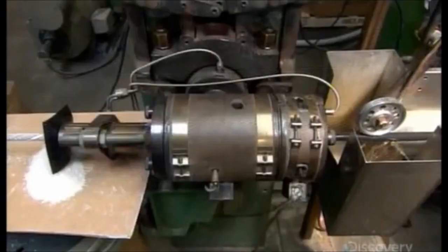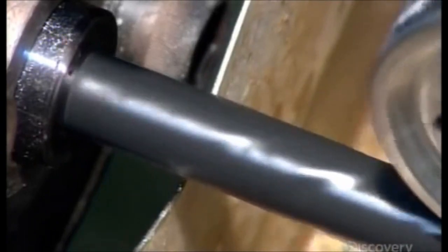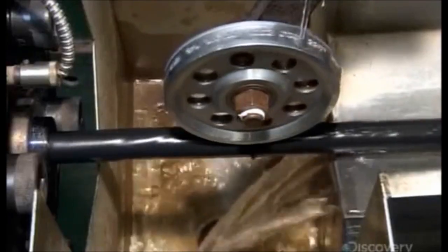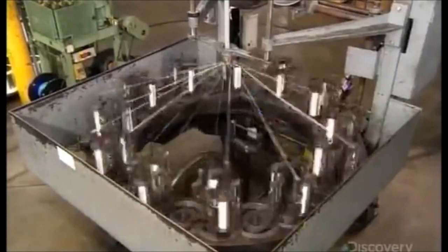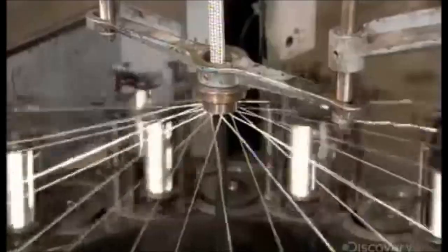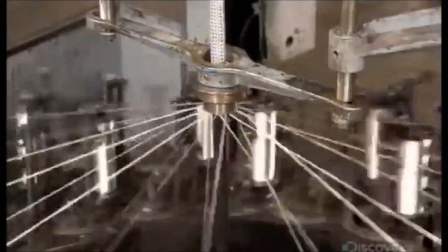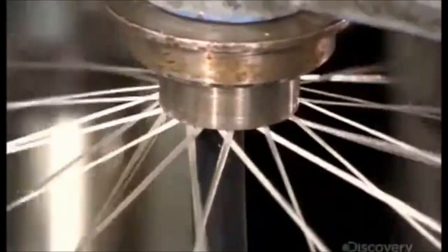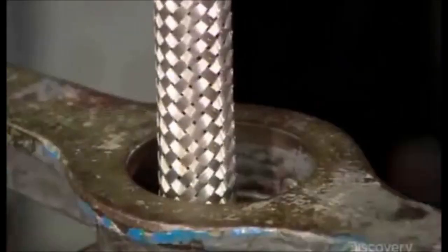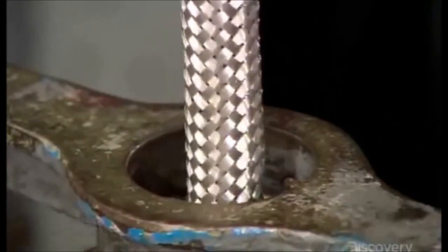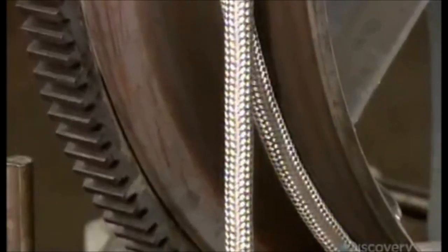Once again, as the cable exits the extruder, chilled water solidifies the molten material into a jacket. A wheel with raised lettering imprints the manufacturer's name and technical specifications into the jacket. Certain jacketed cables need a braided shield to eliminate electrical interference. This machine has 48 carrier spools, each of which holds 10 wires made of tin-plated copper. As the jacketed cable moves upward through the machine, the spools move in a programmed pattern, weaving the shield around the cable.